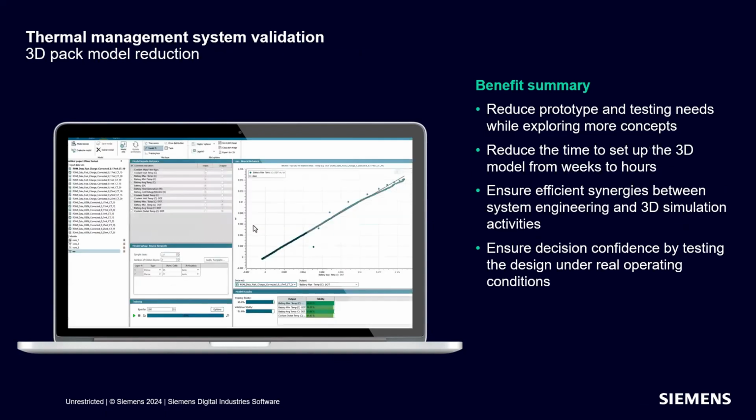Obviously, the 3D type of models can take a lot of time to run. We developed a detailed 3D model to understand the cooling and venting of the cells, the thermal and electrical behavior. However, this comes at quite a computational cost. And this is where we can use our reduced order modeling capabilities to significantly reduce runtime. So let's go into that.